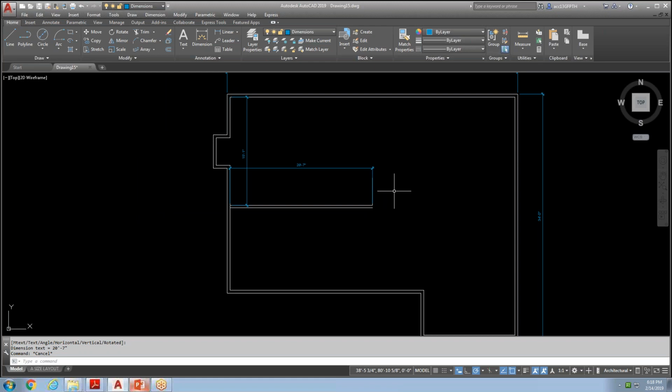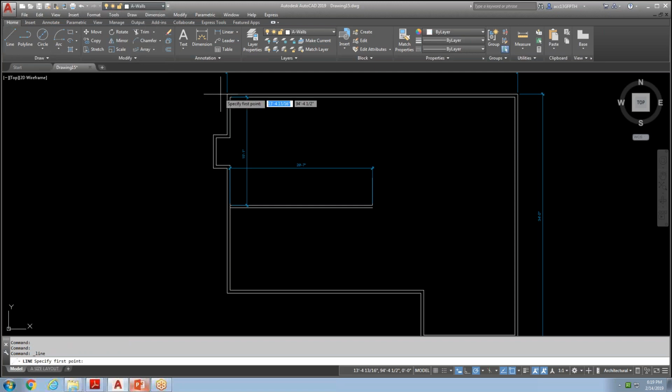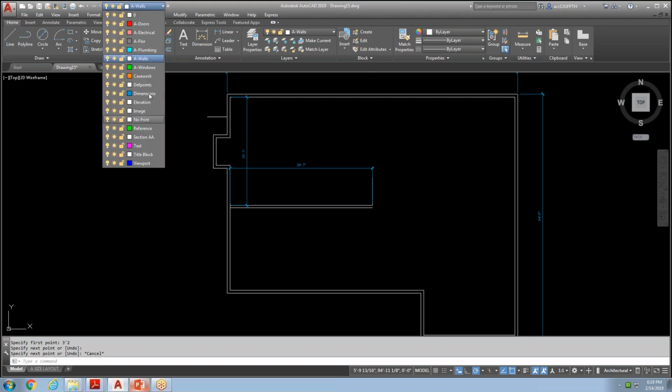Now, one thing that I did include in this drawing is there are some blocks. For instance, there's a 3-foot window block, and I made a 3-foot window block that goes in here. And the 3-foot window block is actually centered at 3 feet 2 inches from the top left corner. So what I could do is draw a line there just to give myself something to align it with. I'm going to do that just to get myself oriented. So I'm going to say 3 foot 2, and that's going to be right there. And then I'm going to insert my window.